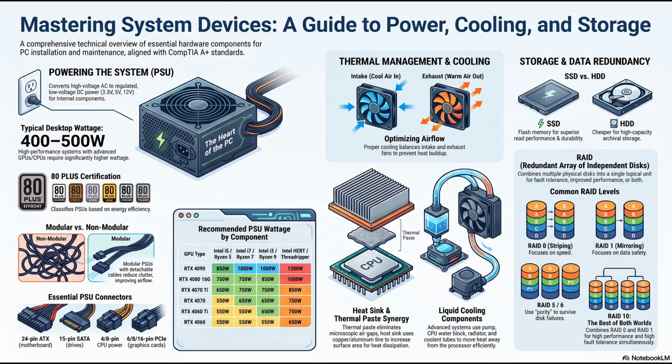It's vital, but it's not a permanent fix, is it? I've heard of older laptops suddenly overheating, and the fix is just repasting the CPU. Because it is a fluid suspension, thermal paste will eventually dry out over a span of several years due to the constant extreme temperature cycles. It hardens, cracks, and introduces air gaps back into the system. Removing the cooler, cleaning off the crusty old paste with high-purity isopropyl alcohol, and applying a fresh drop can drop operating temperatures by 20 degrees instantly.